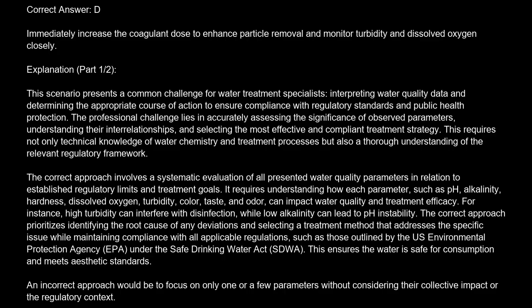The correct approach involves a systematic evaluation of all presented water quality parameters in relation to established regulatory limits and treatment goals. It requires understanding how each parameter, such as pH, alkalinity, hardness, dissolved oxygen, turbidity, color, taste, and odor, can impact water quality and treatment efficacy. For instance, high turbidity can interfere with disinfection, while low alkalinity can lead to pH instability.